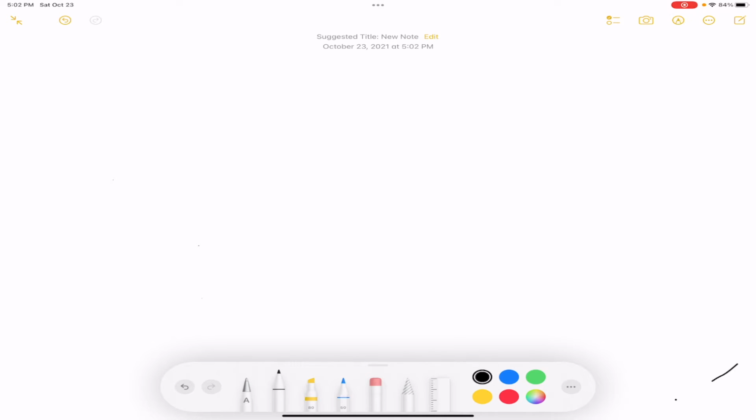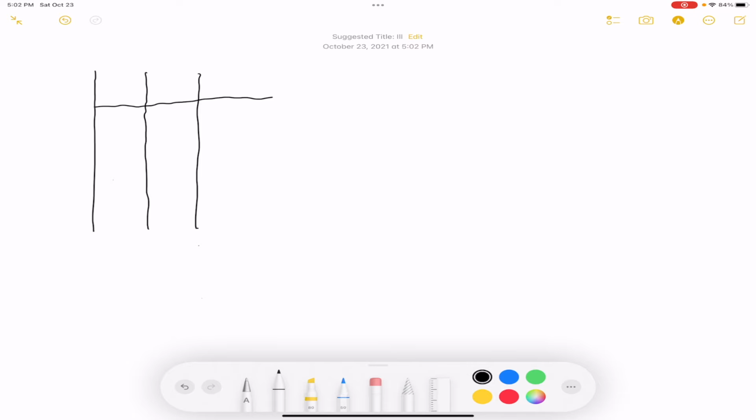So now that we understand how logic gates work, we're going to begin drawing our circuit. Just like we were doing before, we're going to draw a truth table, but since we're drawing a full adder, we're going to be dealing with a case where there is a carry-in bit. So A, B, C-I-N, that's a carry-in. I want to bold that out a little bit.